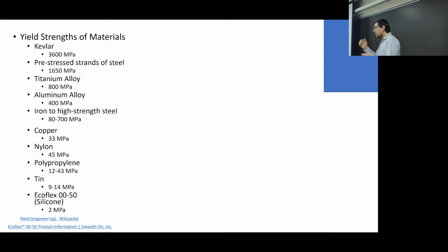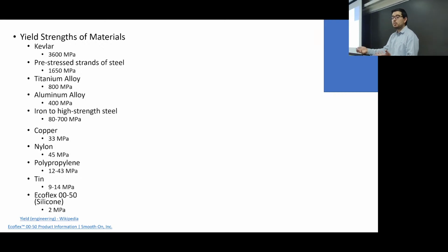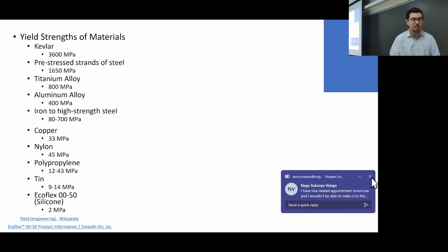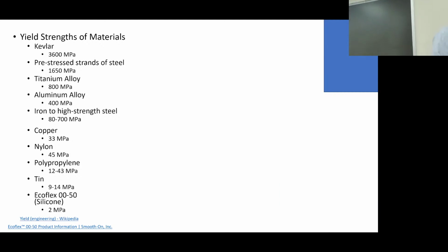Okay, so anyway, we went around on the bar, and we're just measuring the hardness, and then we're correlating that hardness with what the strength of the material was. Okay, say, hey, yeah, this makes sense. This doesn't make sense for why it would have failed here or there.